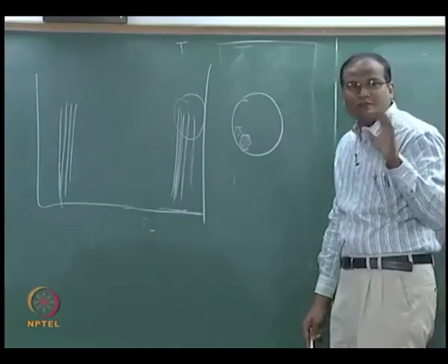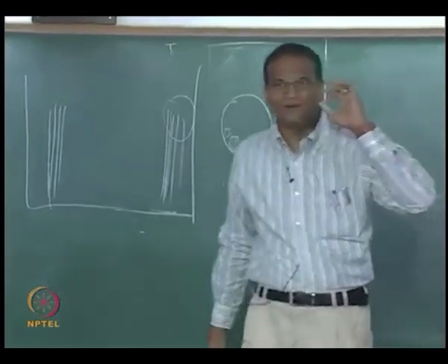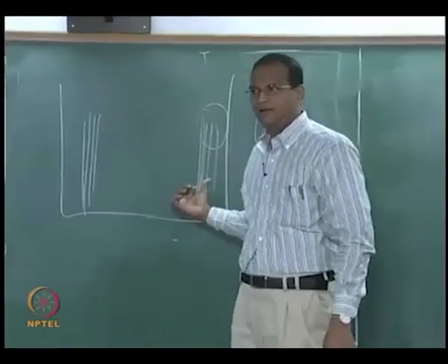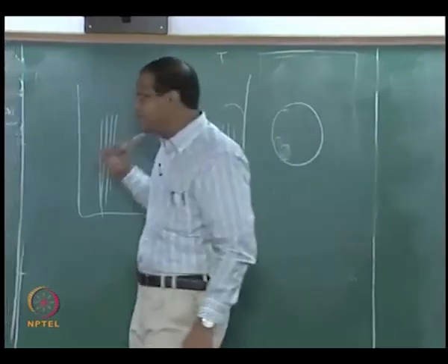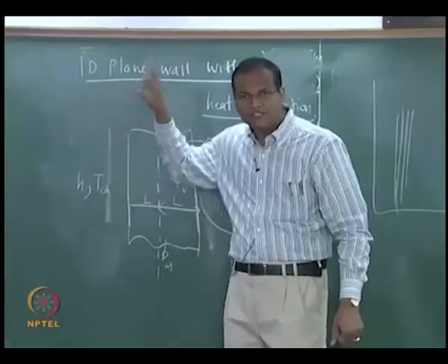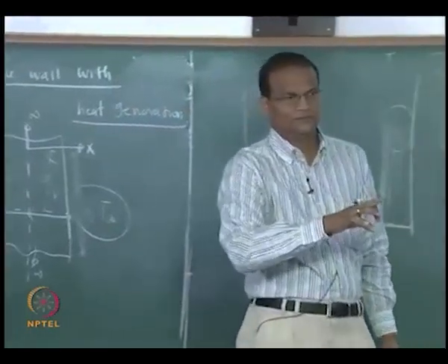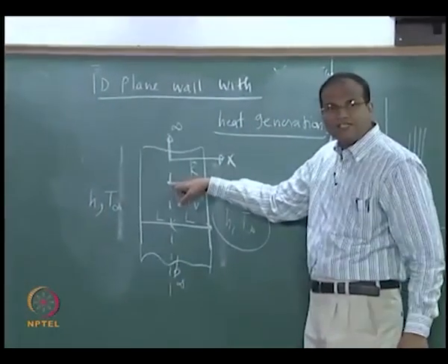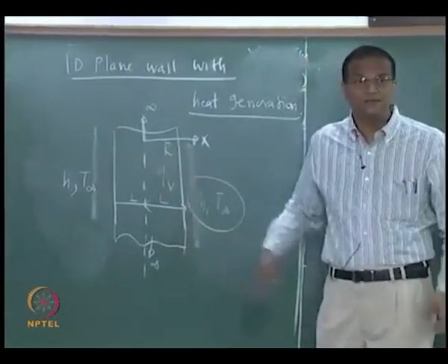In the event of a tsunami or earthquake or a station blackout, this pumping system will fail. When this pumping system fails, the high values of H which you got with forced convection will suddenly go down. Then the temperature will dramatically increase.